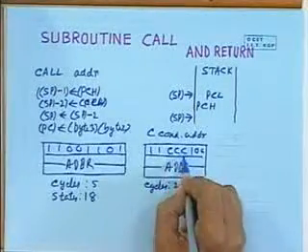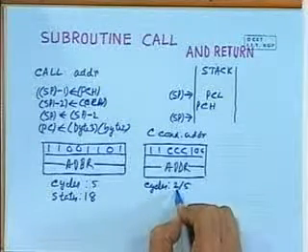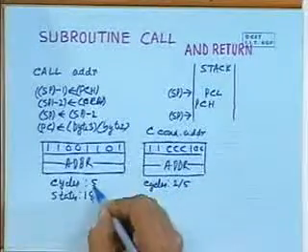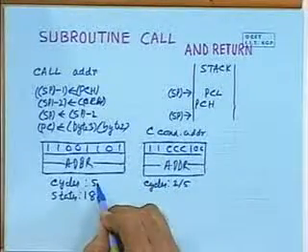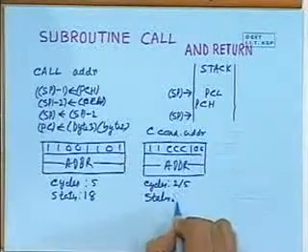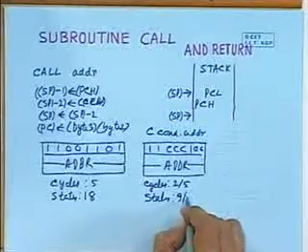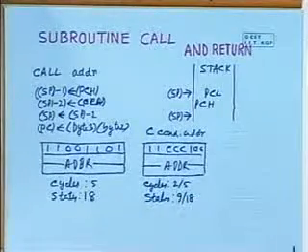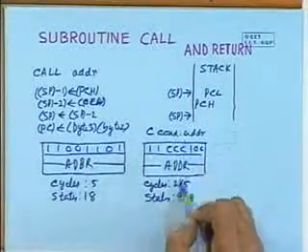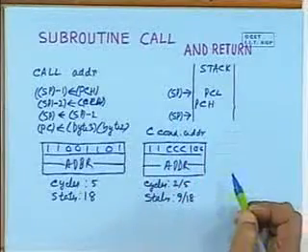When this condition is not satisfied, then the number of machine cycles required is only 2, but when it is satisfied, then you require the same time as the unconditional call, and number of states required again will be varying, 9 or 18. So you find there is some difference in execution times in case of conditional subroutine calls.